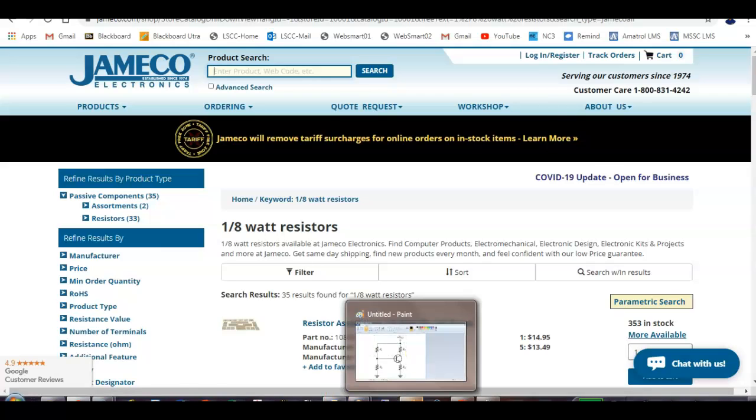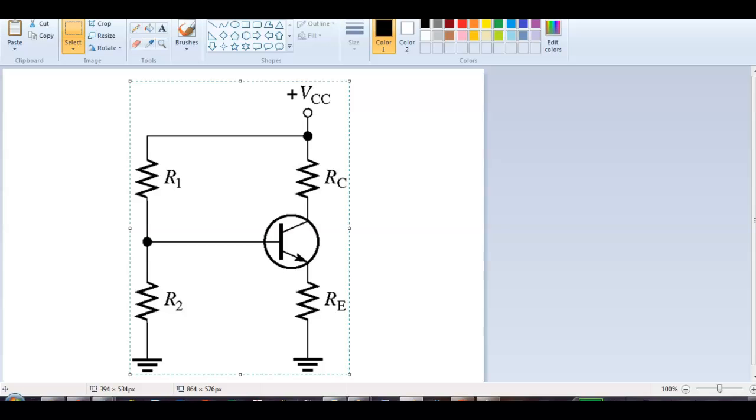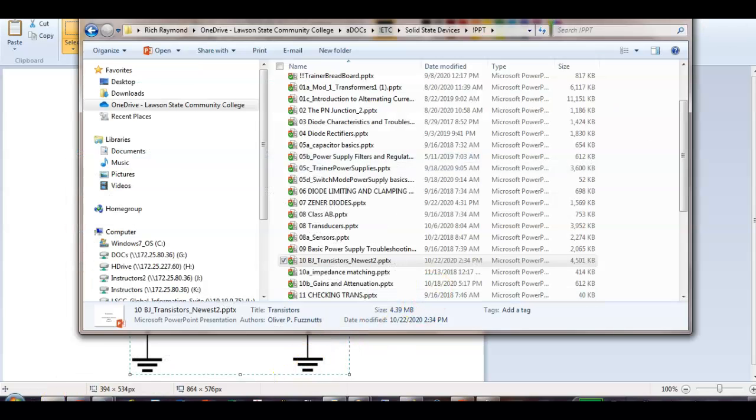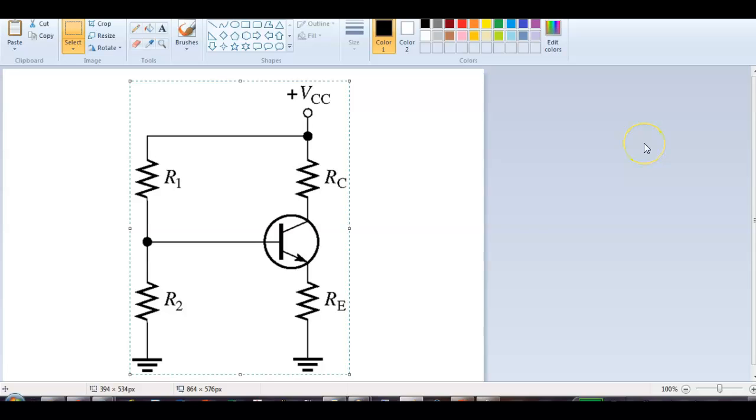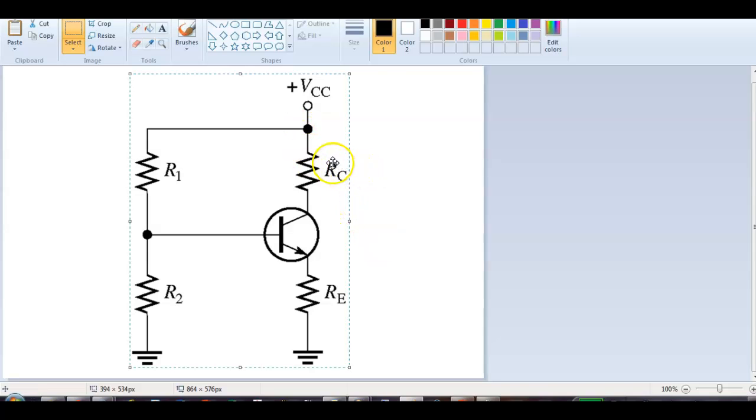So let's see. Okay, one more thing. And we got one more amplifier we need to go through. There's actually 3. We have what we call a common emitter. You'll see why it's called a common emitter? Because it's common to both the input and the output, right? Remember, the input sees that VCC as 0 volts. It sees it as a common. But we're limited in the gain. So the gain is set right now by this resistor in parallel with your load and this resistor right here.